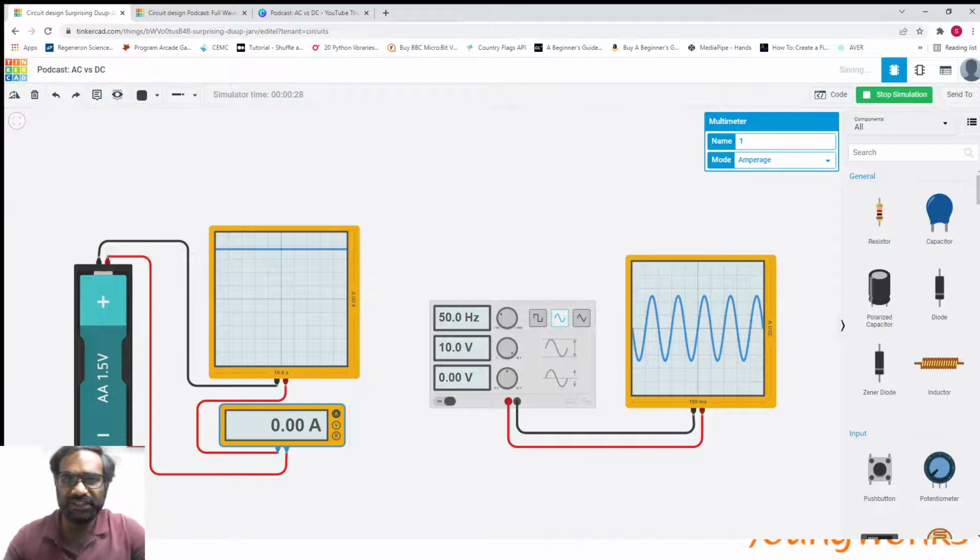On the right, you see AC power, where you can see a sinusoidal wave, and it has the value 50 hertz at 10 volts. You can see the scale is 20, so the top is 10 volts positive and then 10 volts negative, and it keeps switching between the two at 50 hertz, which means it switches from positive to negative 50 times in 1 second. Now, this varies from country to country, but most of them are in this range. In America, for example, we use 110 volts at 50 hertz.